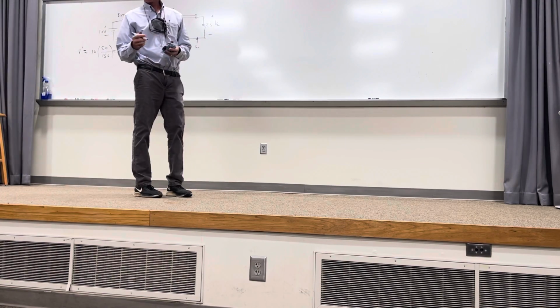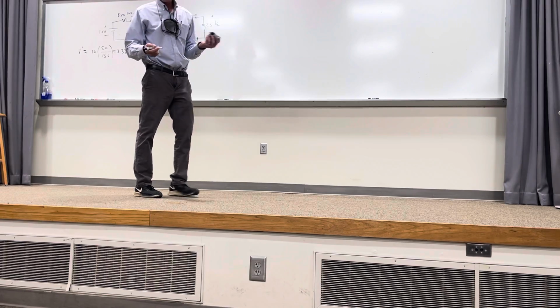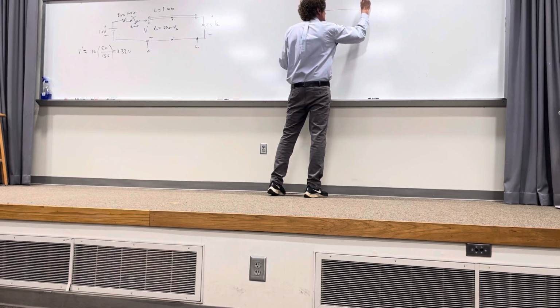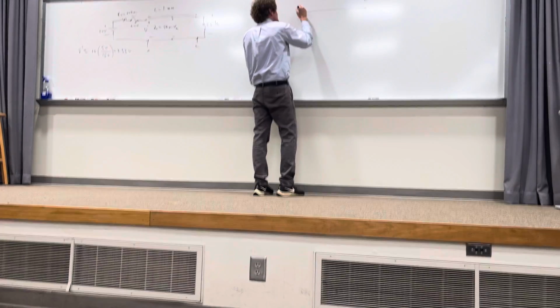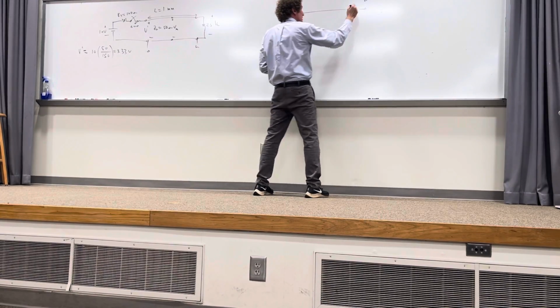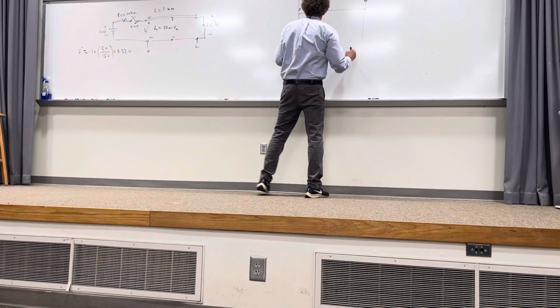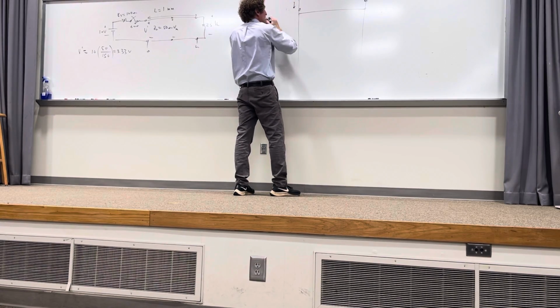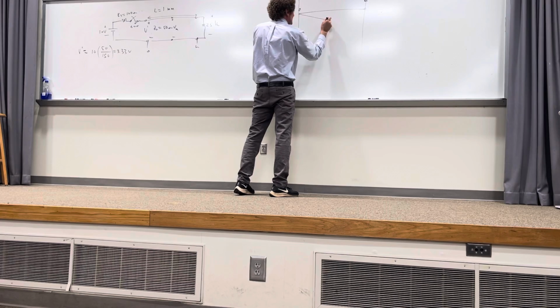Now, we do the bounce diagram by just setting it up the normal way. On the top, you just put a line here. This is L, this is 0. Then here you're going to have time, right? Or just T. And so the bounce diagram looks like this.